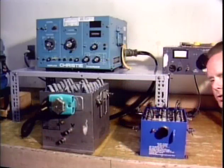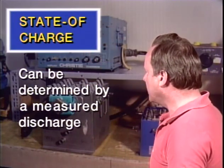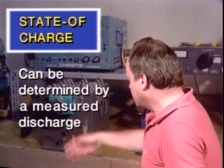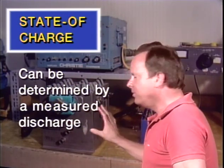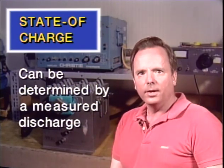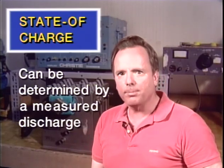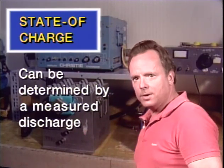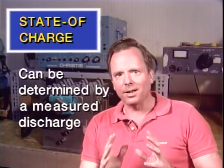Now here's a question I do not like on the FAA written exam. They ask you, how do you determine the state of charge of a NiCad battery? And the answer, the only one that can possibly be a correct answer, is that the state of charge of a NiCad battery can be determined by a measured discharge. Now what they're talking about is you discharge the battery at a specified rate and measure its ampere-hour capacity, then recharge it. Now that might be a way to tell the condition of the cells of the battery, but I don't think it's a very good way to determine the state of charge. Doesn't matter what I think.